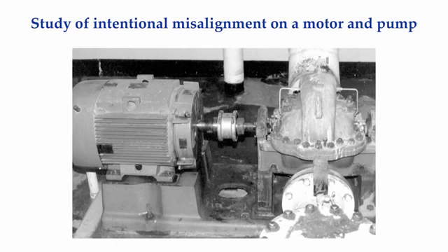A few years prior to the misalignment experiment on a training demonstrator, I did my very first misalignment experiment on a motor-driven circulating water pump. To my knowledge, it may have been the first time anyone intentionally misaligned a drive system and observed what happens to the vibration. Initially, I did it to prove, once and for all, that vibration increases when you misalign machines and that misalignment will show up at twice running speed. Boy, was I in for a surprise.